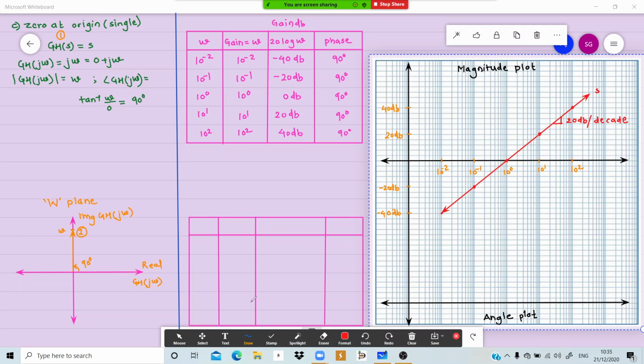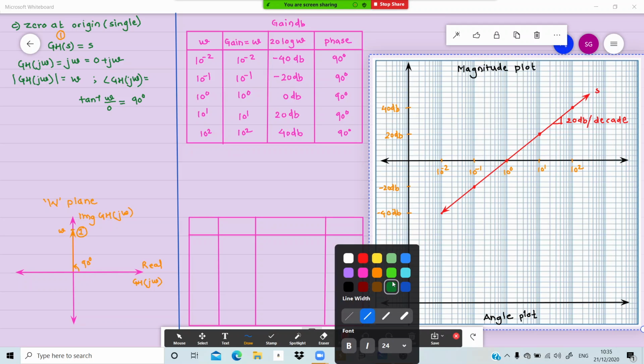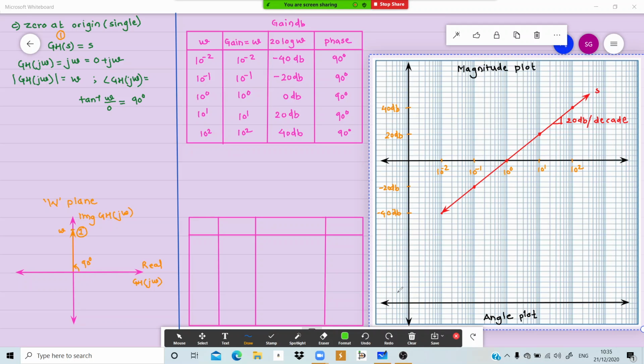Right? Okay. Angle के लिए we'll just say 90. So 1, 2, 3, 4, 5. See, I am taking 5 divisions equal to 90 degrees. Now your choice how you want to take it, right? You may say one division is equal to 90 degrees, but it should be measurable. That's why it's your choice how you will keep the resolution. When you will actually do in the exam, your graph paper size, I mean the Bode plot semi log paper size will be much greater than this. So definitely you will be able to do it neatly, with better resolution actually.